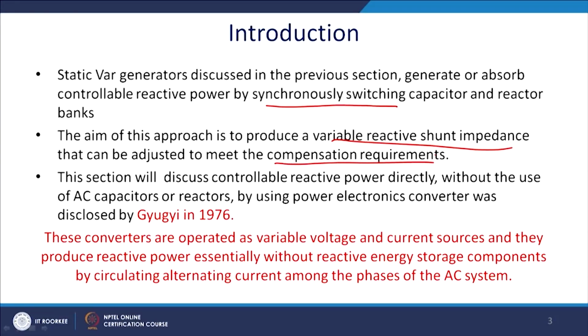You know that P equals sending end voltage times receiving end voltage divided by X into sin delta, in the case of real power generally. So, we generally change the value of X to change the power handling capability as well as the reactive power handling capability and the voltage regulation. This section will discuss controllable reactive power directly. We will not introduce any impedance; we rather control the V2